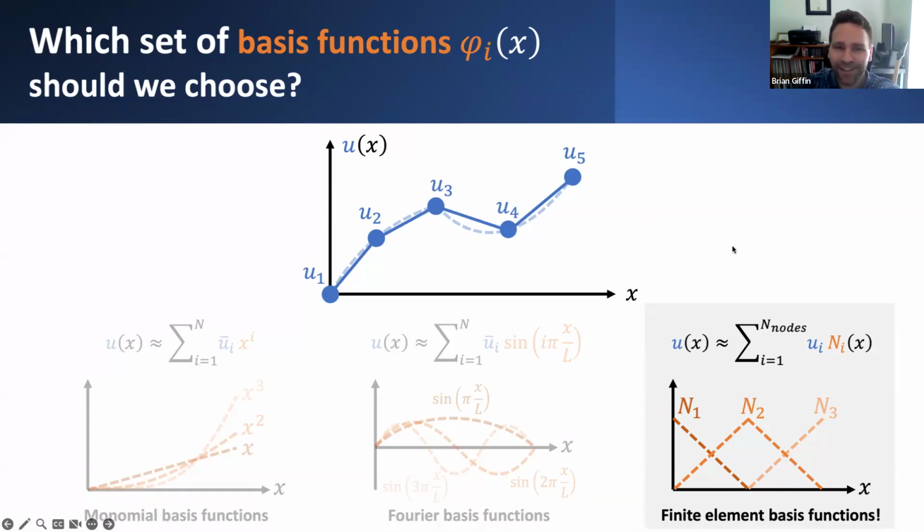So that's the finite element basis for choosing to represent some solution as essentially a piecewise linear function. So relatively simplistic. And you can kind of see that the form of these functions, we'll go into the details, looks kind of funny. It looks like these triangular functions that have a limited range over which they're non-zero.